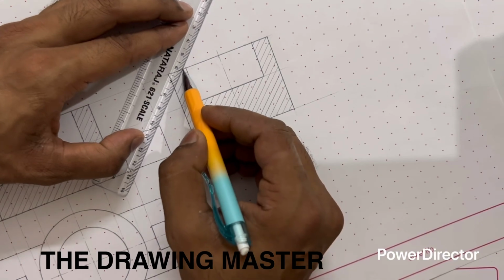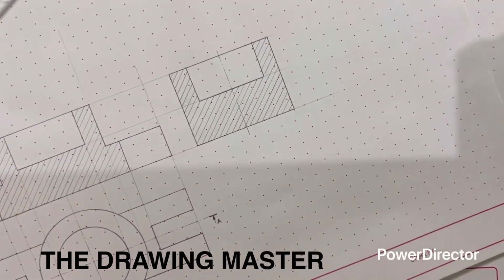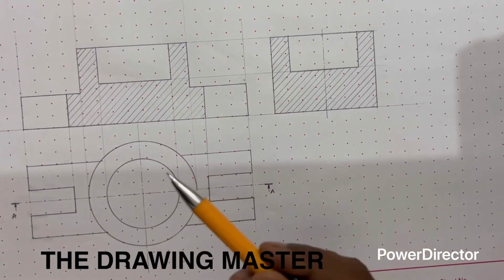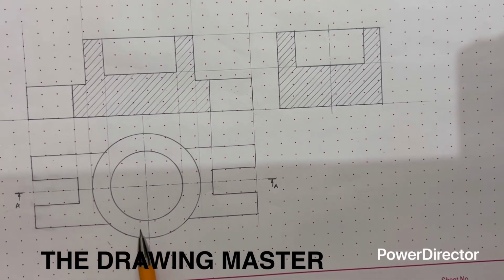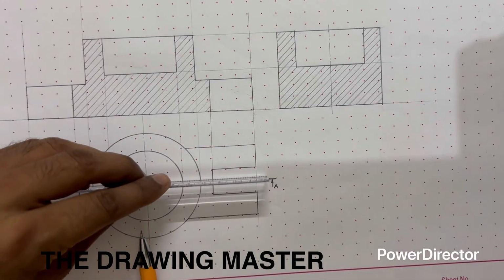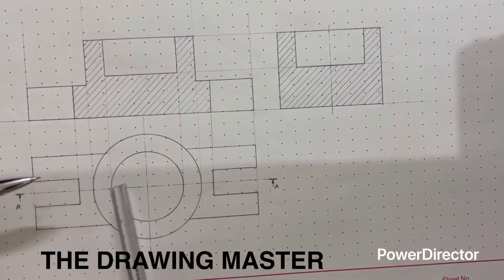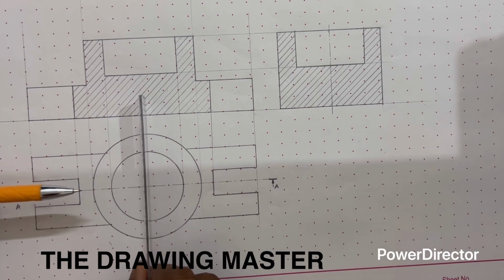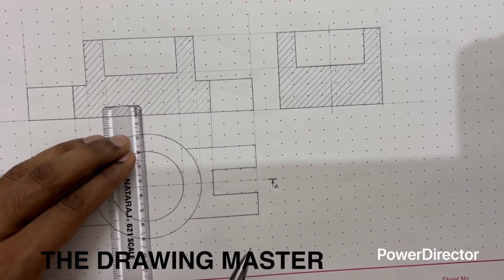Only two things are missing in this drawing. First one is dimensioning. So dimensioning is your task. I have already uploaded one lecture on the dimensioning. The second thing is the cutting plane. If this is the top view, we have projected the front view from this direction, and this was the cutting plane. After cutting this object from here, we have projected the front view. For the side view, the observer is here from the left side and the cutting plane is here, and then we have projected the side view of this object. So here we have to show the cutting plane line.